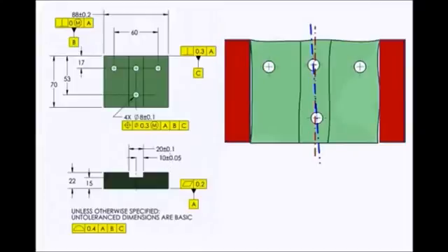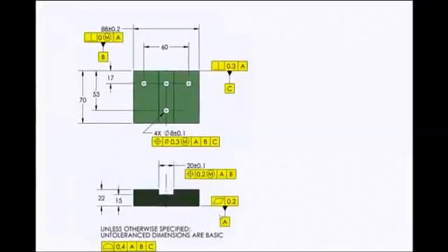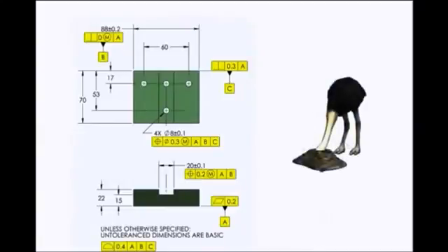And I don't know what the precedence is. Is B supposed to be used as primary or secondary? This drawing doesn't tell you. So please don't use those half dimensions, especially on these tolerance dimensions like the 20. Do it the right way and control its location using position. And stop burying your head in the sand with those old methods.